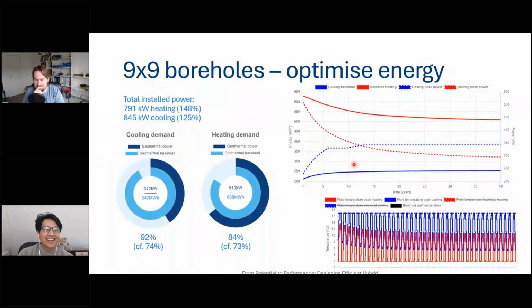Okay. How does the model of the heat pump factor into the simulation? Do you use a fixed COP number, or is there a way to vary COP based on the supply temperature? So the way it is done now is by using a constant SCOP. We're working on advancing towards selecting a heat pump with part load data and temperature data. We're discussing with the manufacturer because it's really sensitive data, but now it's a constant SCOP.